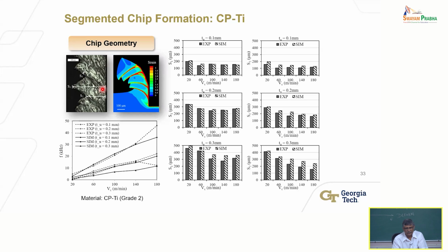Strain rates matter. How fast you're deforming the material. Because sometimes for the same material, under certain speeds, you will not see this phenomenon. Like in certain steels, you only see the step of a severe plastic grain refinement at very, very high speeds, not at low speeds, right? So it's a bit more complicated. I can't give you one answer that, hey, this is under this condition, this is the only factor that matters. But I'd say the properties of the material and the deformation rates are two important factors.